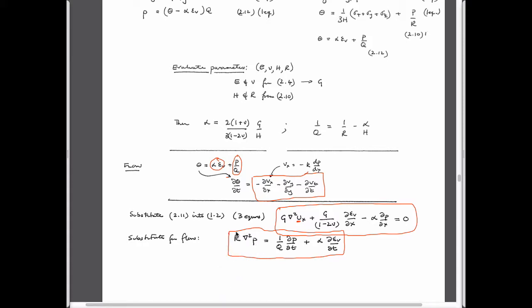And again, the Darcian behavior. When we've talked about porous media flows, then basically what we've done is we've taken these two terms together. This 1 over Q is kind of a storage matrix, right? We've written these things typically as K del squared H is equal to specific storage times H dot. And so the heads are pressures, so this is some kind of storage term in hydrology, or 1 over Q is just one of the Biot coefficients.